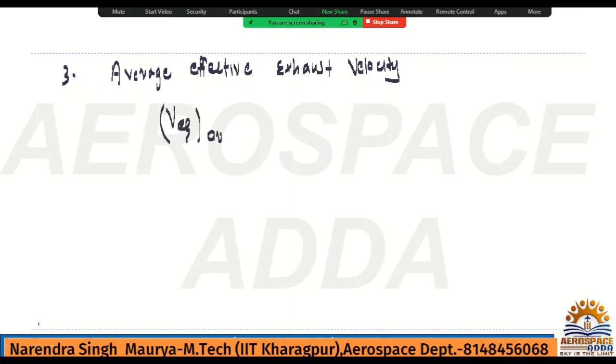How to get this average? That time I had written the formula. It is the total thrust divided by the total mass flow rate, m dot total. So what is the total thrust? First it will be for the main engine plus thrust for the booster.